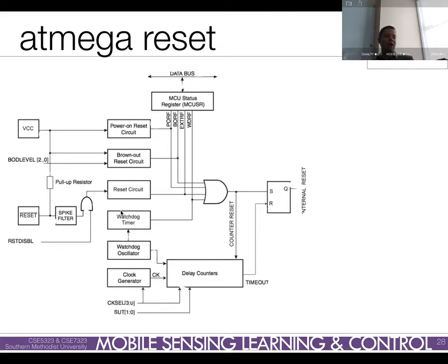Right? And if ever that gets to a certain value, bam, you get a logic 1 that goes into this. What is that? OR. It's an OR gate. So if any of these happen, bam, this OR gate goes high. It sends a signal down to this delay. And then it also goes into this. Does anybody know what this is? It's a latch. Yeah. Now we're rocking this thing. We're good to go, right?